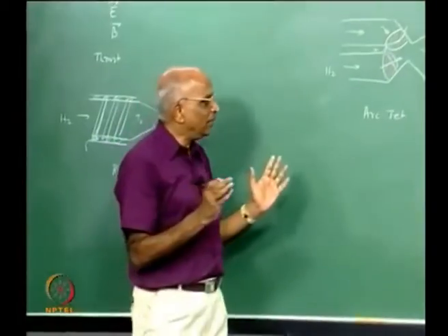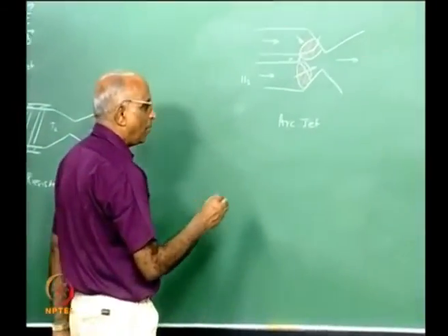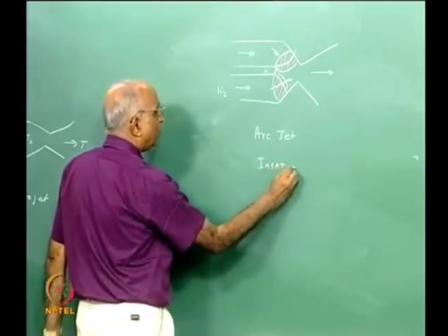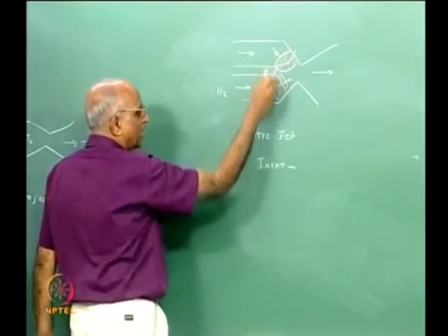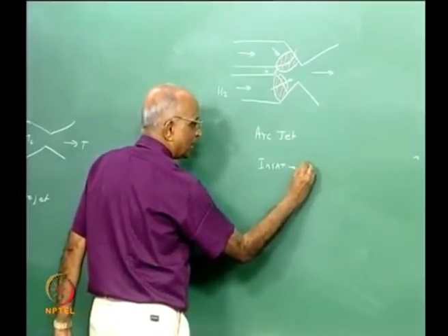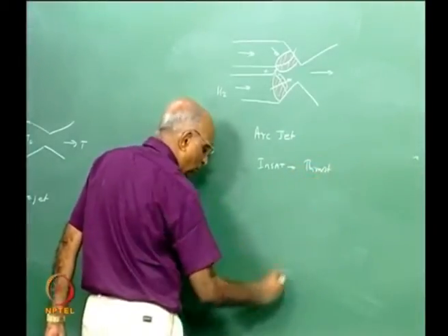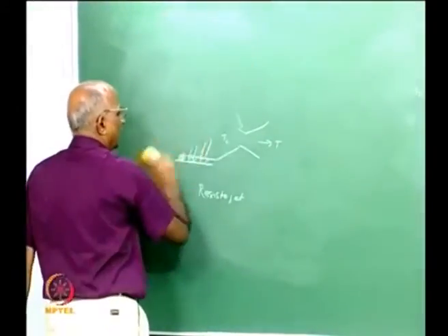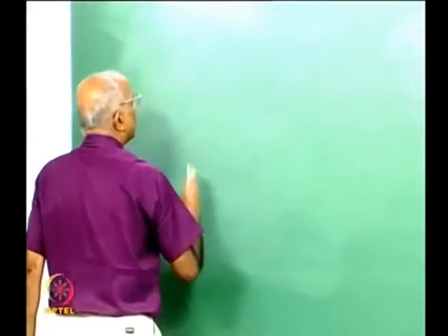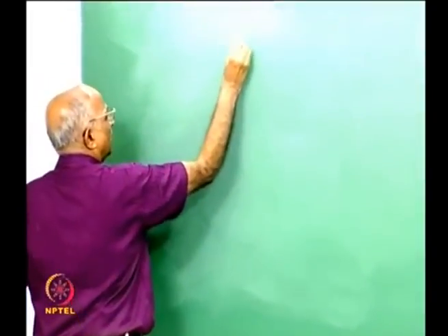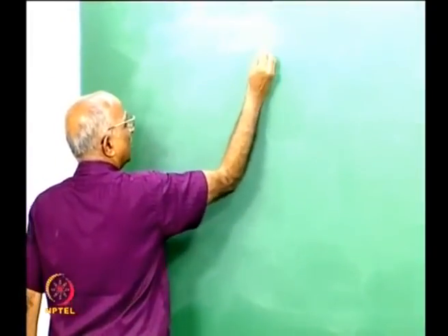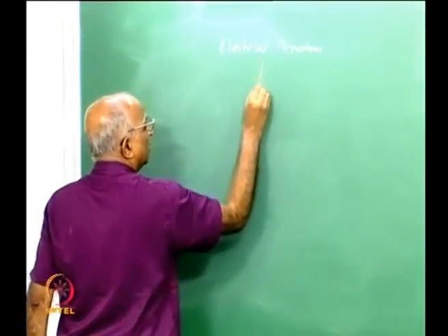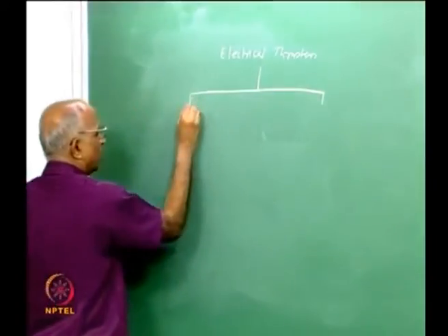In fact, when we made the first prototype, or a discussion on the Indian national satellite, INSAT satellite, we thought we will use ammonia as a gas with an arc and use it to generate thrust. Therefore, to conclude the discussions on electrical rockets, we can say electrical rockets are essentially, we could call them electrical thrusters, since they generally can be used only for low thrust.